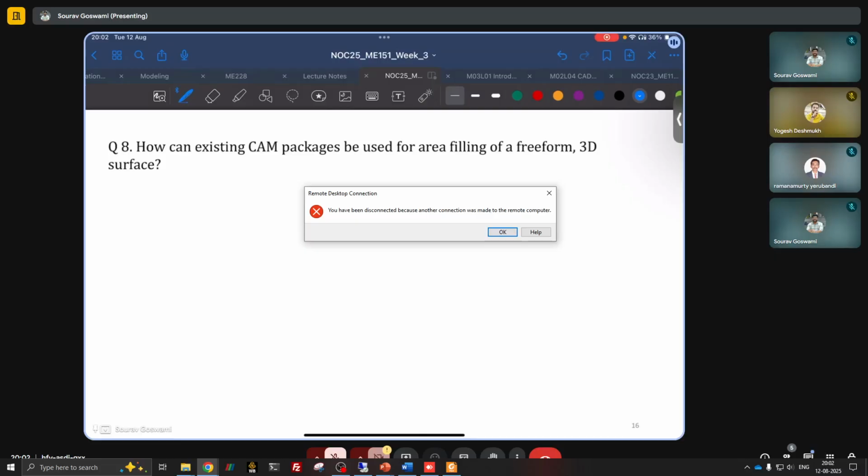The only difference is that now there are some additional commands for start of print, end of print, say arming of the laser head, retraction of wire for checking of contact errors and others. But the motion of the deposition head is still controlled by the same CNC commands which are used for machining. And thus, there is a great potential of existing CAM packages to be adapted for filling of free-form 3D surfaces or 3D printing.